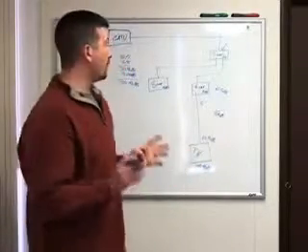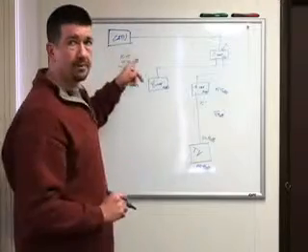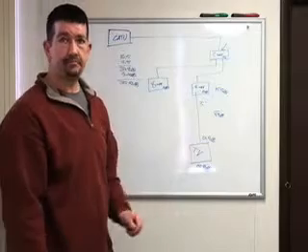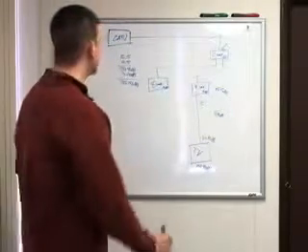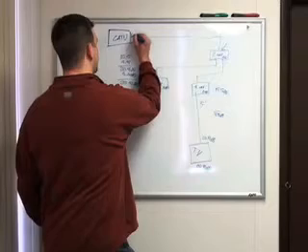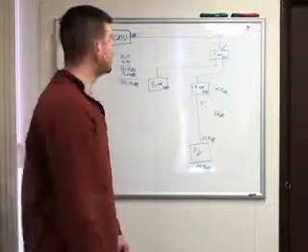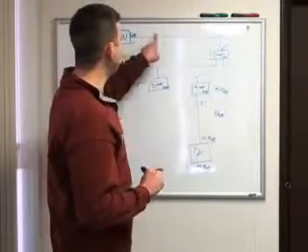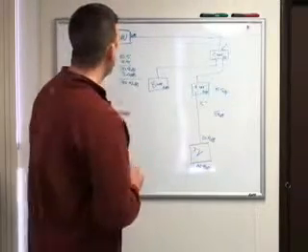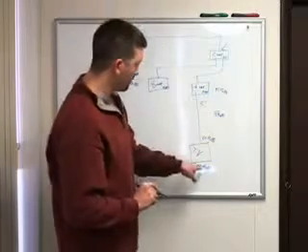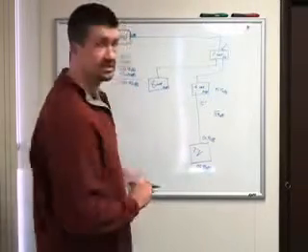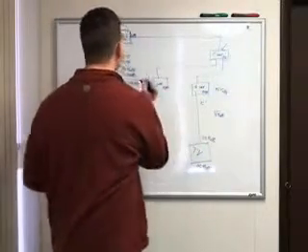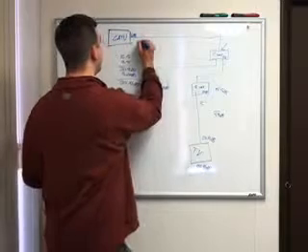So now we need to calculate what we need to do from our cable company to make sure we have 25.41 dB at the input of our two-way splitter. Now let's say in this case that our cable company is supplying us with 6 dB of signal. So in order for us to figure out how much signal we need to go into the amplifier, we need to take 25.41 and subtract the 6 dB from it. So that would give us 19.41 dB.